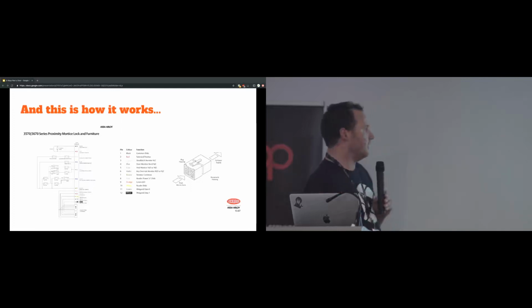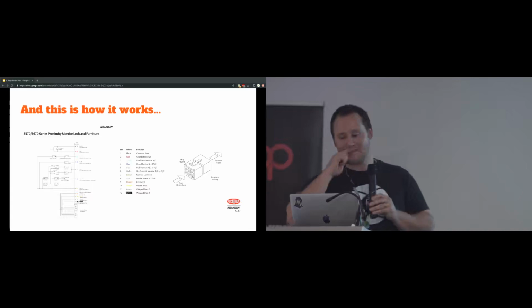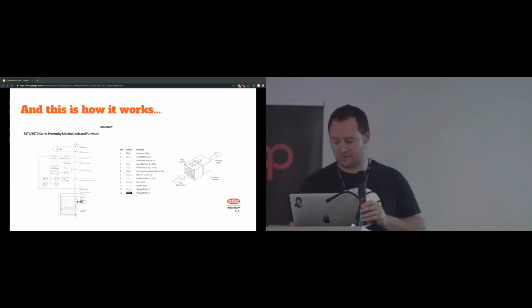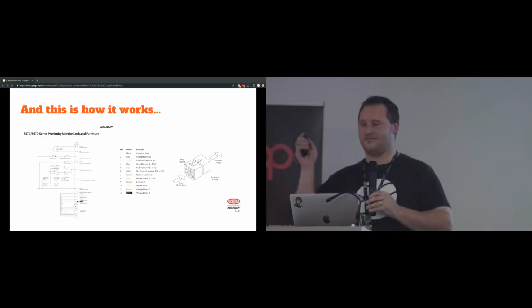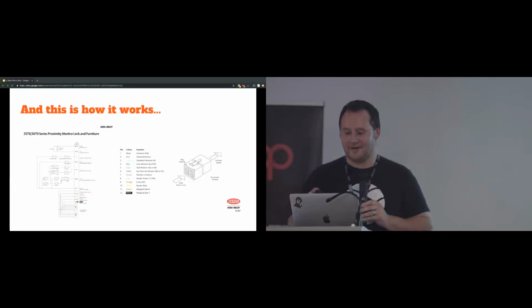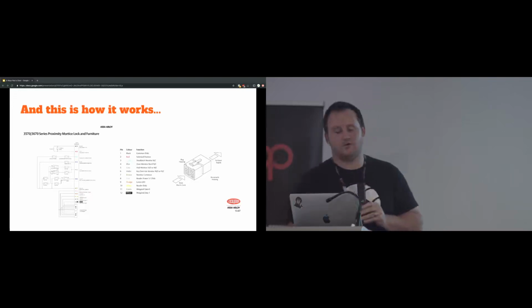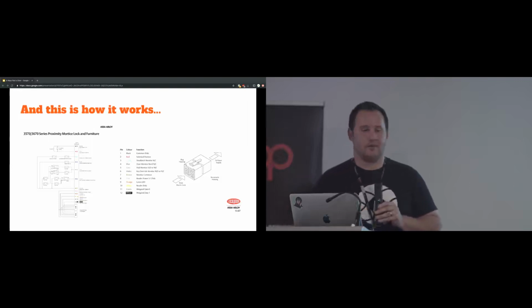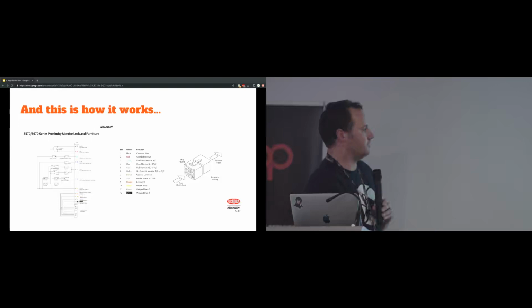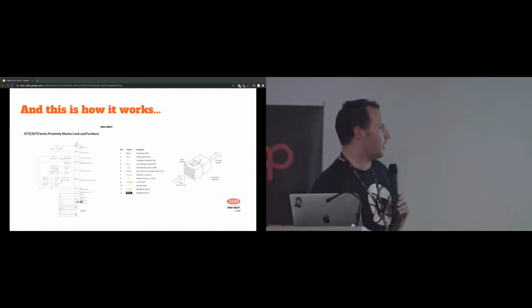So here's the wiring diagram. It's probably too small for you to read. At this stage, we're just interested in pins 1 and 2. These guys over here on the plug, red and black. Standards for wiring are great. Make it so easy to find stuff like this on a wall. So pins 1 and 2 are the common 0 volts, which is basically ground, and the solenoid positive. It's incorrectly spelled on this, which is kind of funny because it did come straight from Assa Abloy.